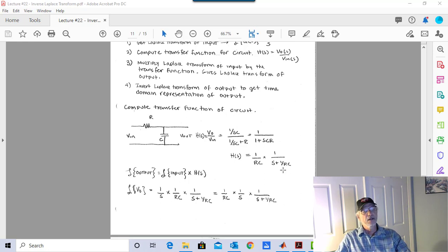And then what I'm going to do is wiggle the format around just so it'll look nicer when I do my Laplace transform inversion. Now, if you don't do this, you'll figure out that you need to when you get there, but I'm just doing it in advance because I've seen this movie before. So here's the transfer function.